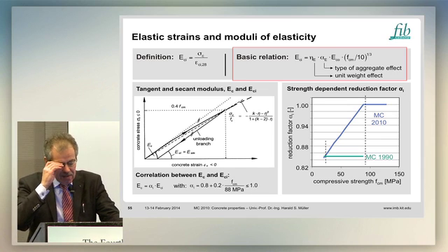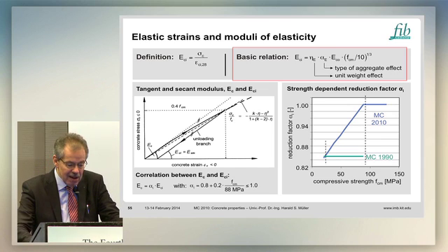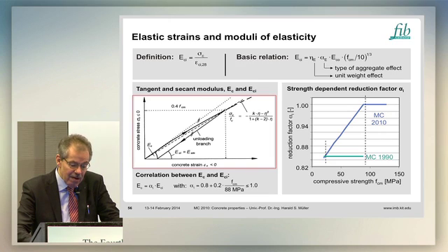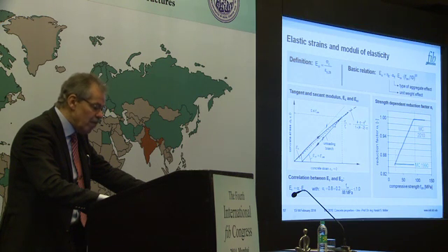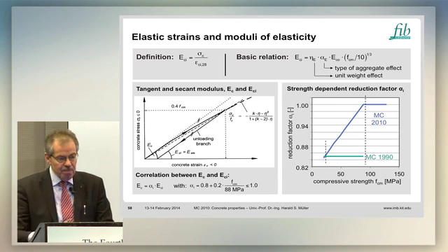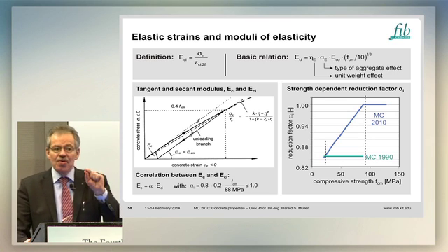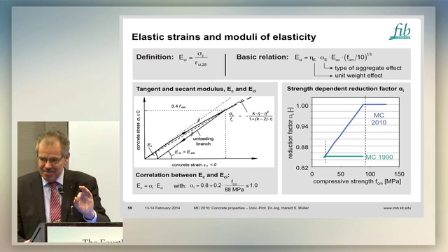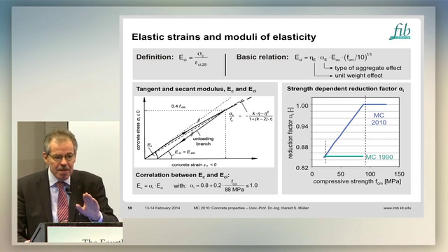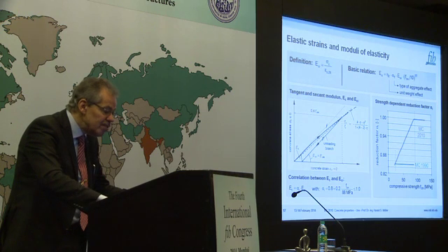What is important in this context is shown in this diagram here. This is a stress-strain diagram for concrete. So if you have a loading of a virgin concrete and you do an unloading, suddenly you end up with some plastic deformations. I already said at this point, these plastic deformations will be tackled as part of creep. So if you run an analysis where you do not deal with creep, you need not the tangent modulus of elasticity, having no plasticity included.